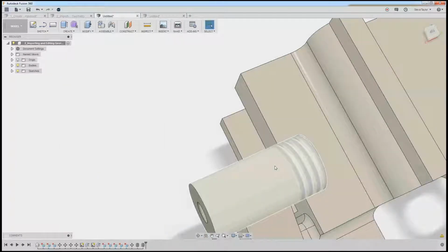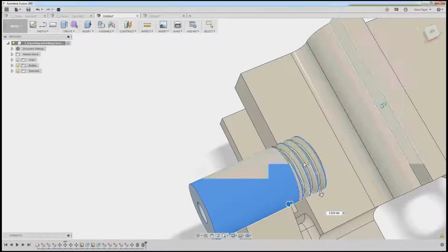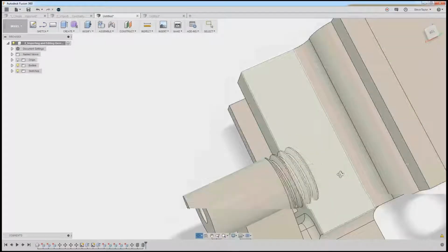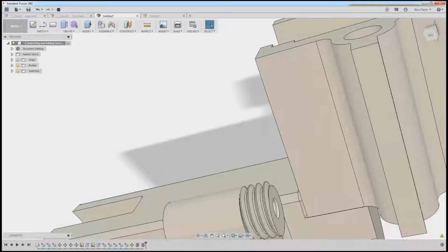However, if you're into 3D manufacturing, additive manufacturing, 3D printing, the problem is when you go to print it, it's only visual, so you won't end up with a thread. But one of the things that is optional in that thread tool, so if I went back to this, the outside one here, is to actually go modeled. And what this modeled option will do, if I press OK, it will actually give me a physical thread model there. So having this option for 3D printing is essential.